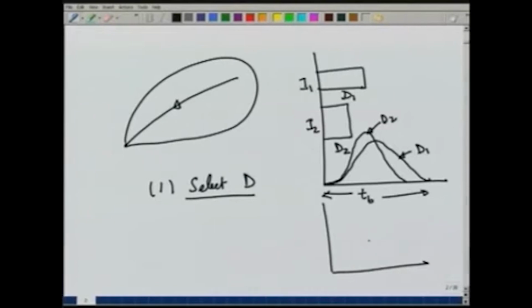In fact, if we look at an ideal or theoretical unit hydrograph, assume it to be rectangular, then we can see that the volume of the rain falling over the catchment would be equal to the volume of the direct runoff at point A. Now, let us, for example, take this peak flow Q as 100 meter cube per second, and let us say that the time base is 40 hours.